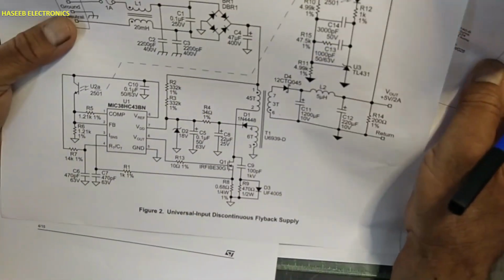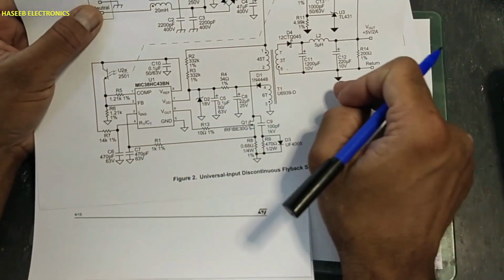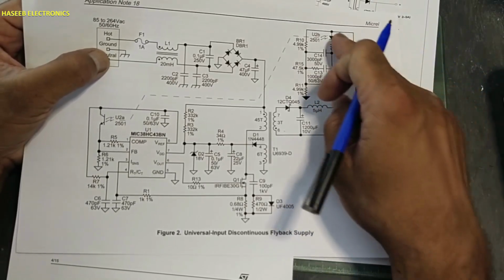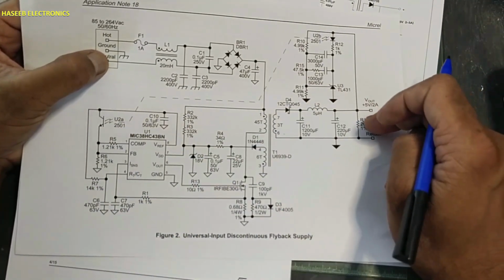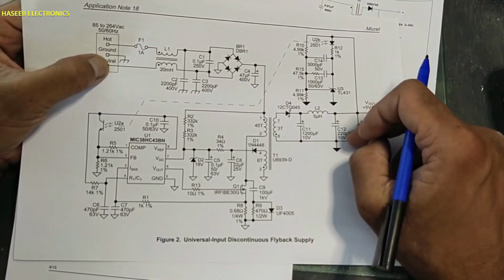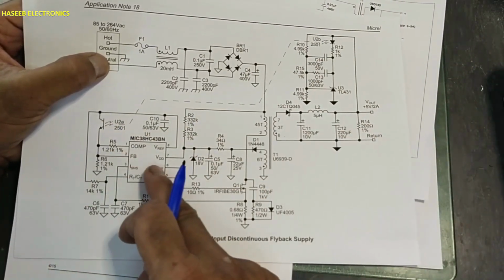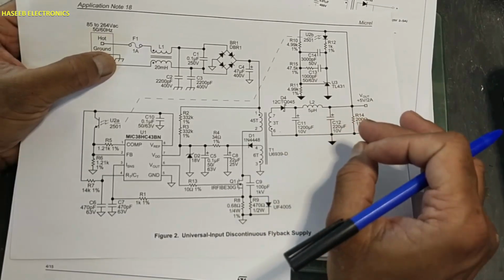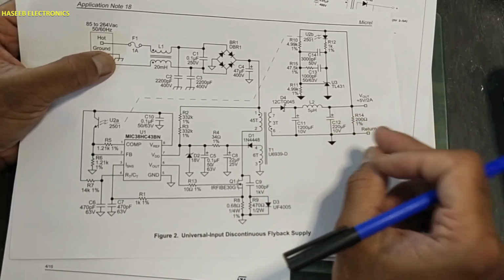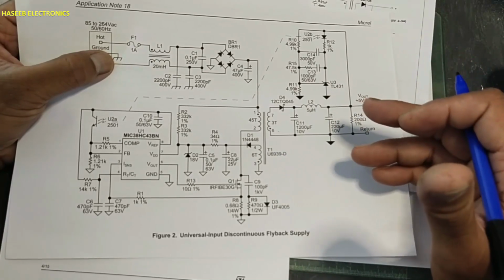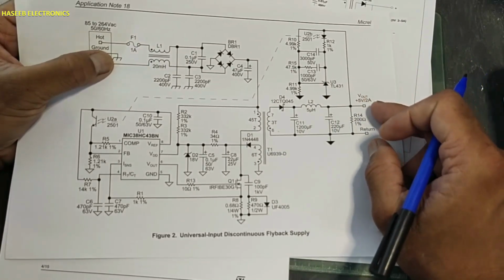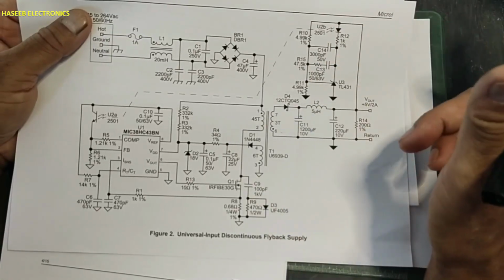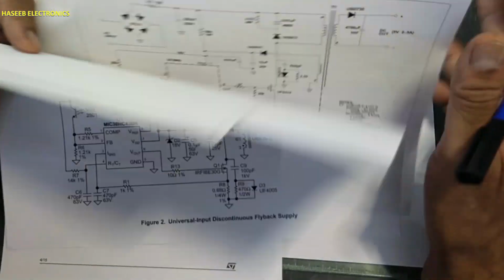But if we have an optocoupler based feedback network, when the output voltage is maintained in the output, we receive feedback. As soon as the voltage drops, it will provide feedback to the IC that the voltage has dropped. Using this technique, 2% regulation can be achieved in the output. 2% tolerance is acceptable, and it will detect load transitions faster compared to a primary side feedback network.